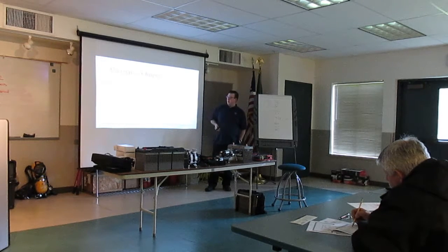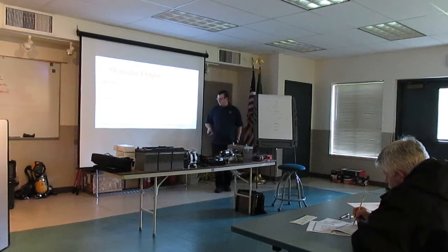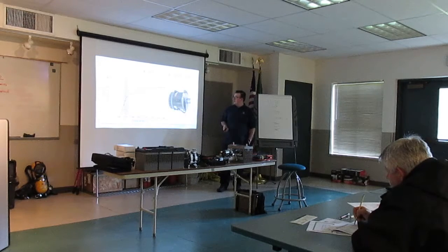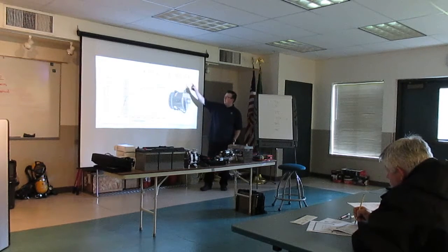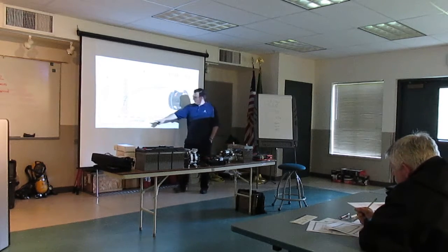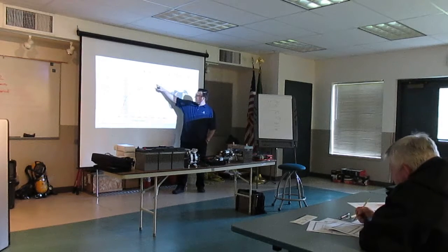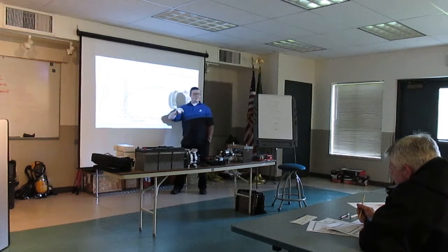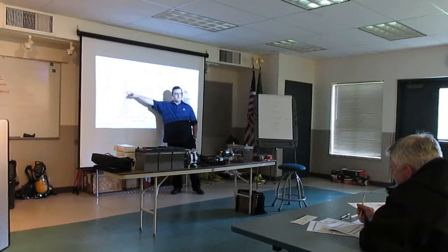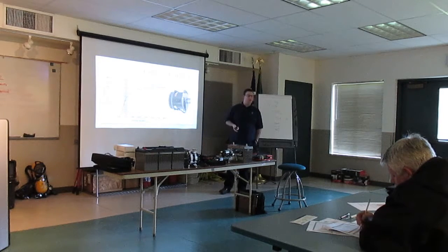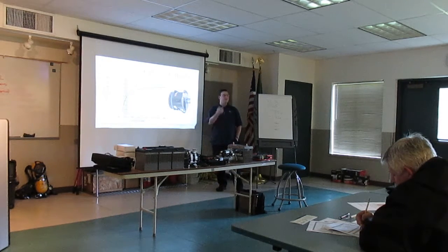Generally, your RPM ratios are 3 to 1. So 3 times the alternator RPM is your engine RPM. The most important things are your output at idle and your output at high temperature. So here we have our C505, 527, 531, 534 models, this style alternator. We have our alternator RPM, and our two curves, our cold and our hot curve. And right about 2000 RPM alternator, we call out idle. That's idle in your engines, because if you think 2000, 2100 alternator RPM, at 3 to 1, that's 700 for your diesel engines.